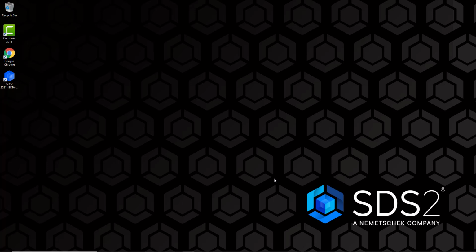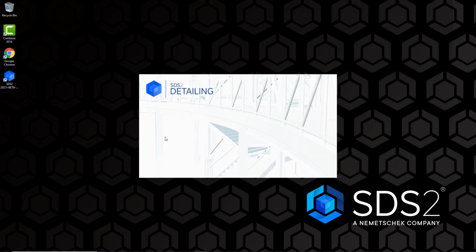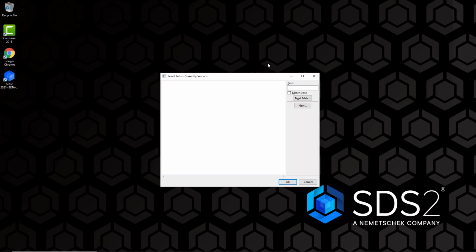At this point, we're ready to get our new project created. So if you have an icon on your desktop, let's go ahead and open up SDS2. You can just click on the SDS2 2021 icon, and you'll be greeted with this select job window. The reason we're greeted with this window is because we don't have any jobs created in SDS2 currently. If you did have a job created, you would go directly to the home screen of SDS2.